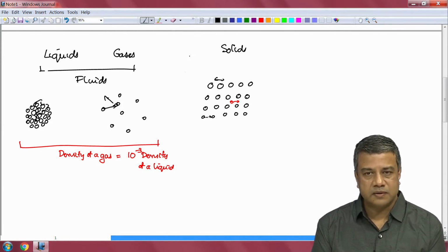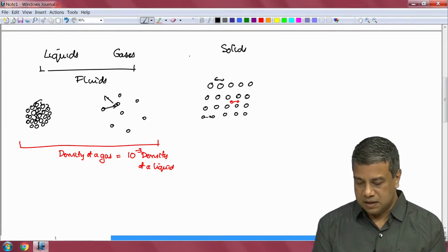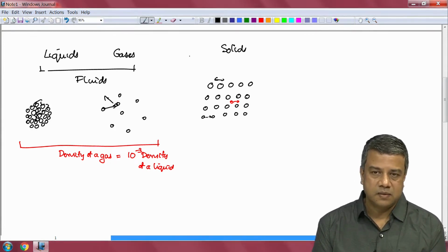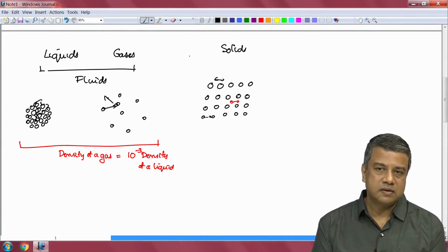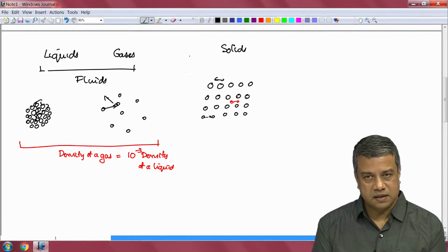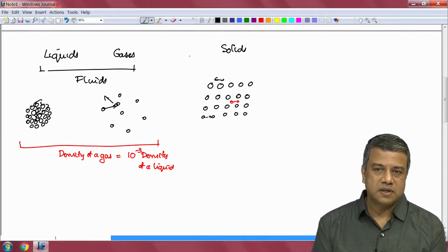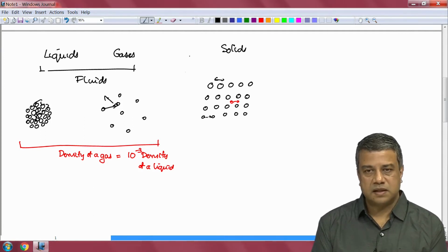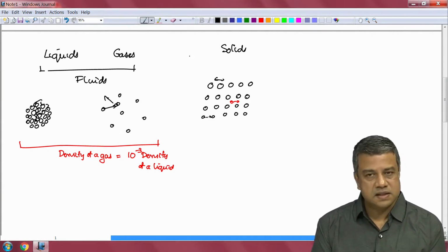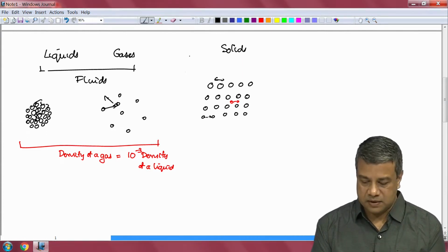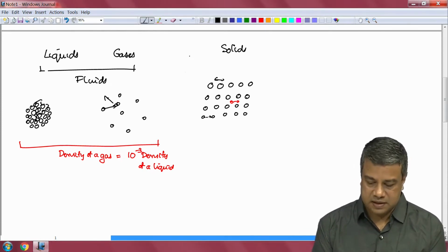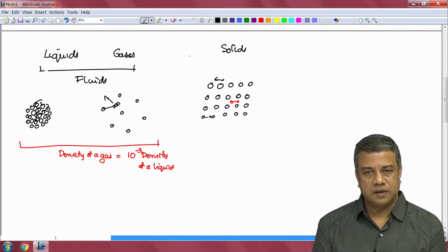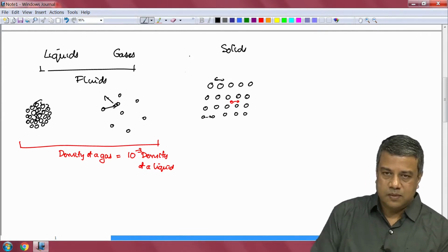The fundamental difference between liquids and gases is the spacing of the molecules. In liquids, the molecules are approximately 1 molecular diameter apart, and therefore they are densely packed, and nevertheless the molecules do not have permanent fixed locations. They diffuse throughout the liquid, and because of that it is possible to move materials relative to each other. That is, motion of materials relative to each other requires motion of the molecules of those materials relative to each other. In gases, the distance between molecules is approximately 10 times the molecular diameter, and molecules interact due to instantaneous collisions in the kinetic theory of gases. The time of an interaction between molecules is much smaller than the time between interactions of molecules.